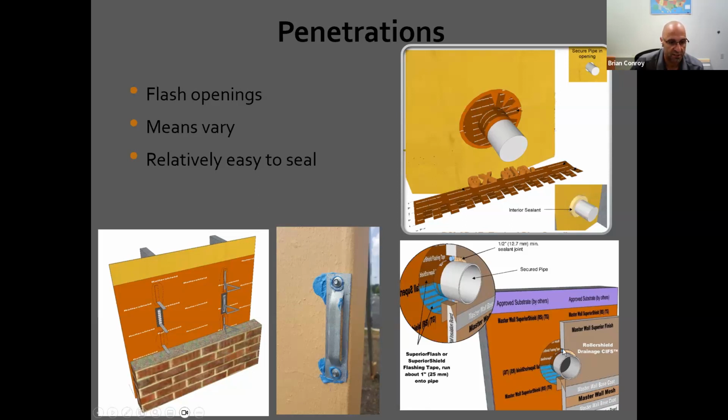Down here, you can see a sealant and backer rod and caulk on the exterior side. A lot of times people think, I could just punch a hole through that wall, no matter what the cladding is, and not have to worry about anything because we have already flashed the wall system. Yet you really have to make sure you flash these pipe penetrations, because the air that's being sucked in will suck in any moisture on and around that pipe penetration.